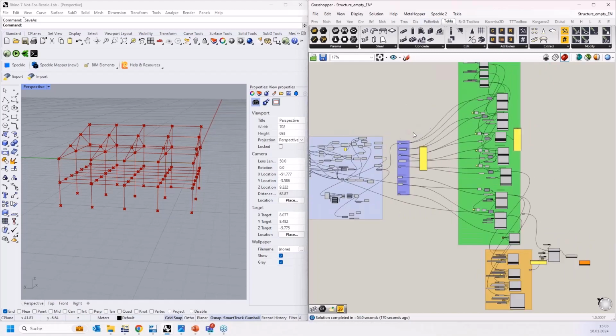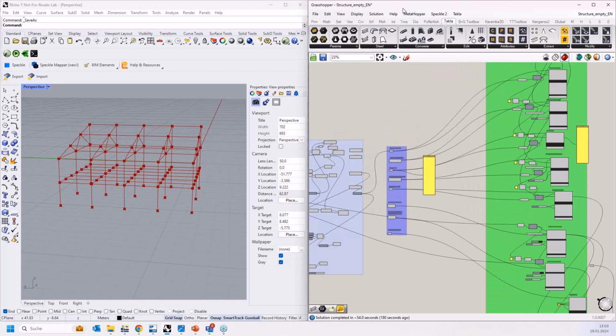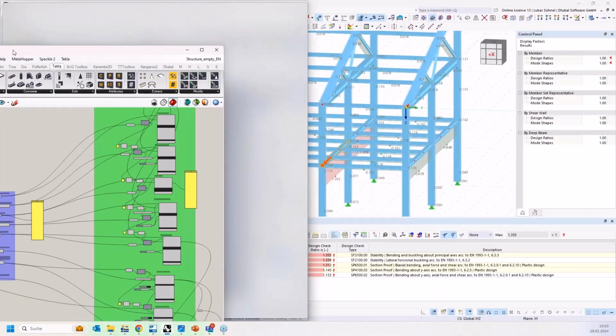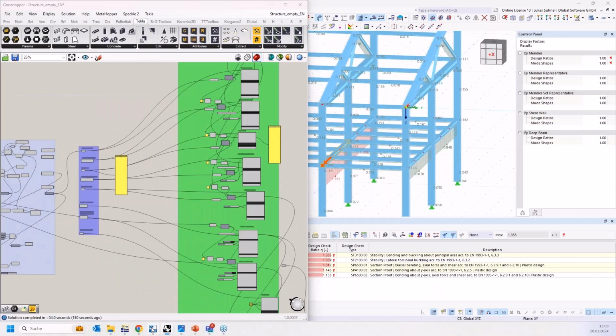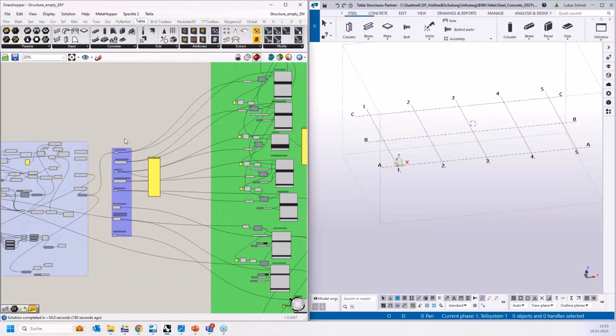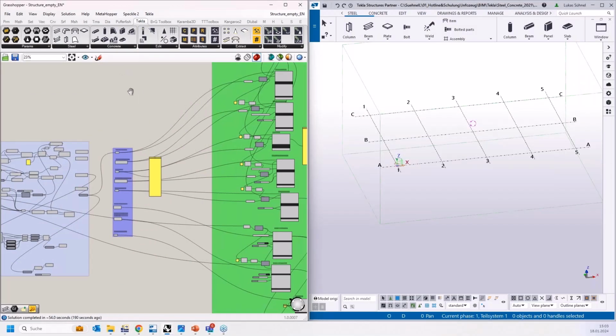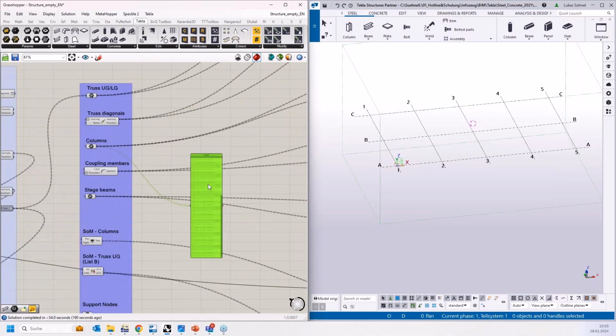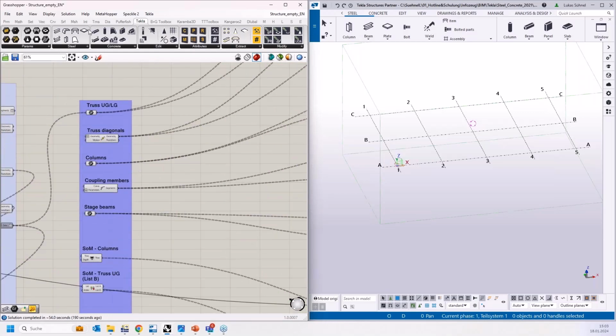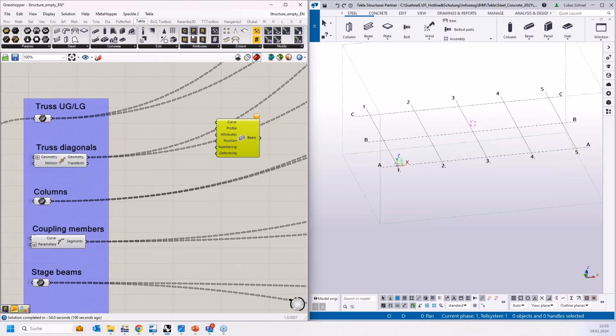And it's not as complicated. You can do the same thing again. Therefore, I have Tekla here now on my right and Grasshopper on the left, and I can simply use the beam component, for example, from Tekla and the profile catalog component to define a section, for example, the HEA 300.